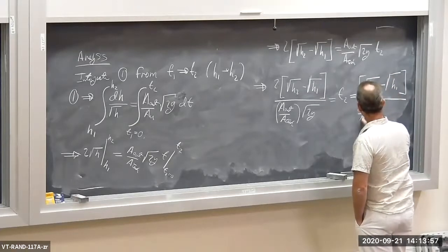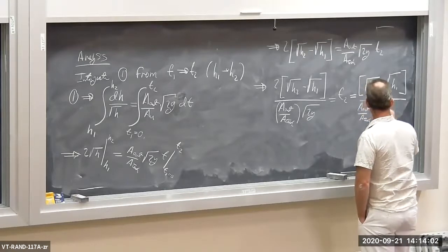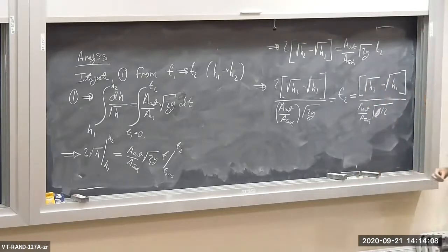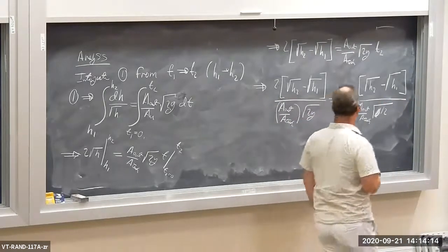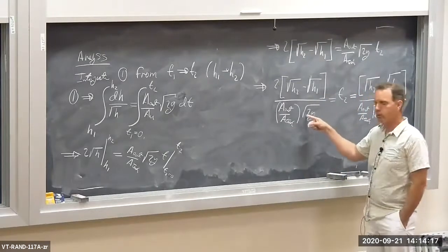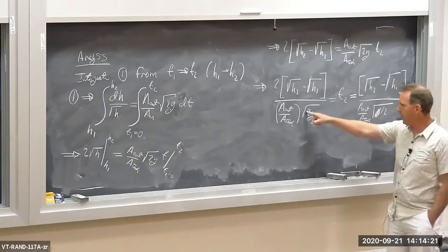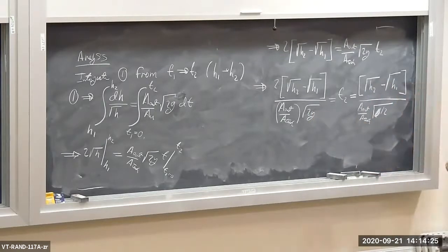A out over A tank, and then I've got square root of g over 2, gravitational constant over 2, okay? Divide top and bottom by 2. It becomes a 4, or a 1 over 4 when you pull it into the square root, and that cancels out partially with the 2 in the numerator. That's where the g over 2 comes from, okay?